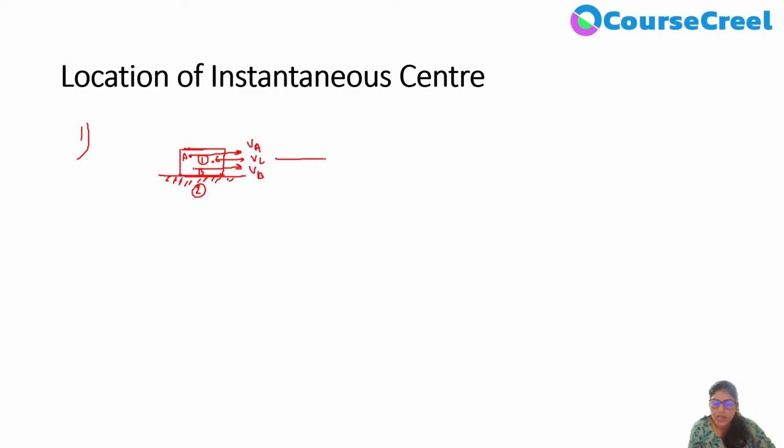So suppose this is the direction of rotation and this is the direction of motion. So every velocity will have direction in the same direction, okay? Because this is the direction of motion and it will have the same velocity. Each and every point will have the same velocity. Why? Because it is on the same link and there is no rotation. So the instantaneous center will be marked at infinite position.